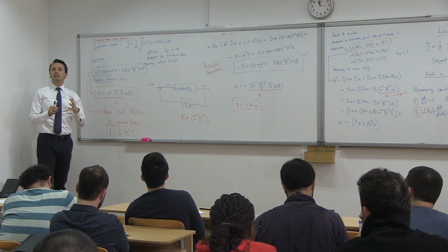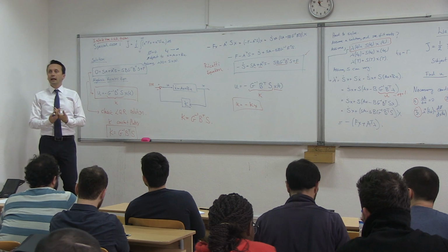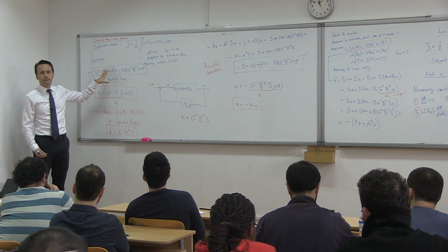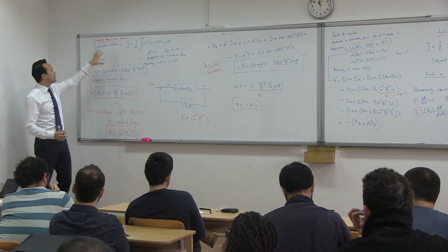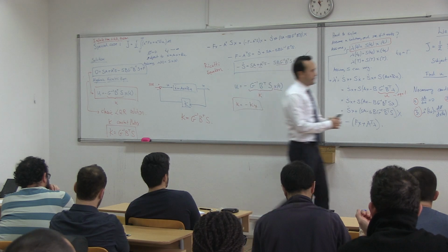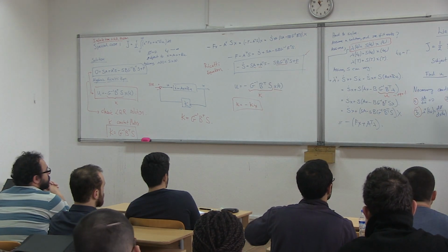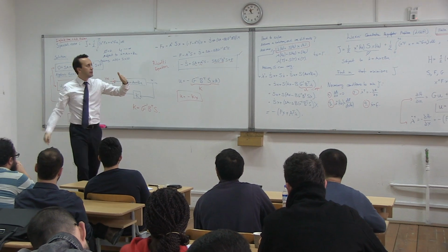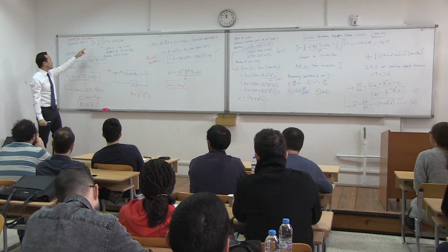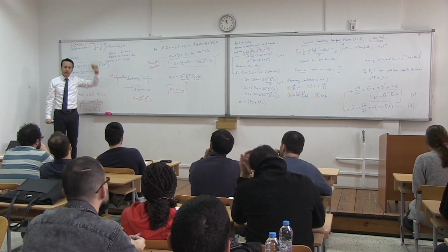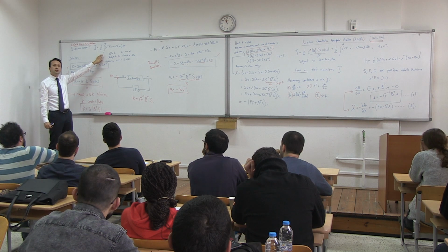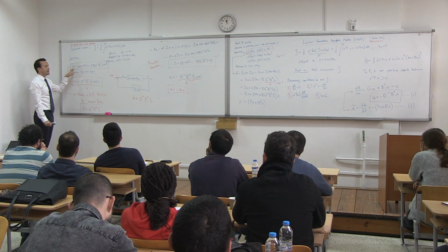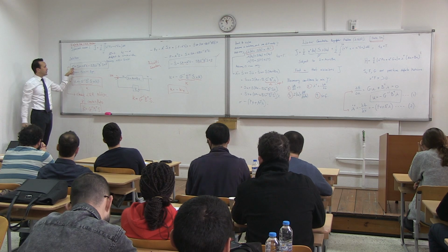And if you would ask somebody in the industry to calculate an LQR gain, this is what people would calculate typically. Okay? There's a distinction between the infinite time LQR problem and the finite time LQR problem. I call it the finite time because this goes to T final. It has to have a stationary point at the end. This here is the infinite time problem because it goes to infinity. Okay? And the solution of this one, though it is somewhat more useful in industry because it goes to infinity, is actually simpler because it doesn't have the differential equation.